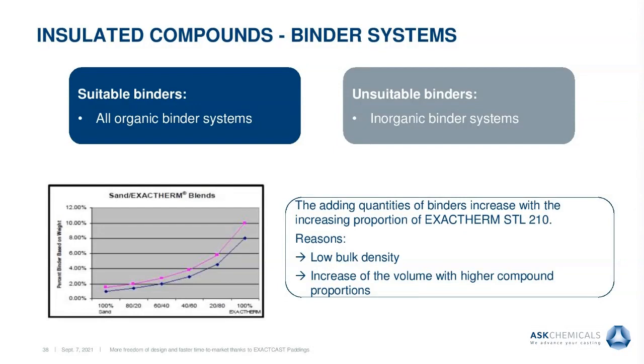In principle, all organic binders are suitable for that process. You can also use inorganic binder systems, but they will raise the thermal conductivity, and the surfaces could also be not as nice as with an organic binder, especially in long solidification times and high temperature alloys.